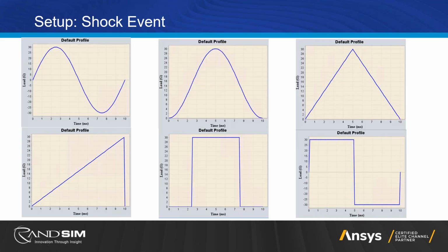And then on this next slide, here are the other available default pulses that you can therefore adjust the loads and decays to. But so you're not just limited to a sinusoid, you have a number of different, full sinusoid, triangle, sawtooth, square, etc. And so you can really kind of put it through its paces and try a lot of different shock events outside of just a simple pulse.